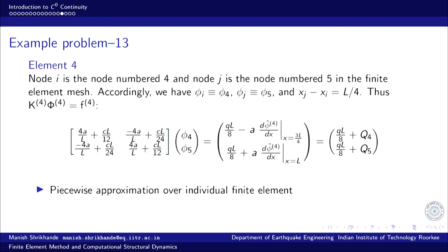For element number 1, we developed a linear interpolation between phi 1 and phi 2, and developed the linear approximation for phi over element 1, and then evaluated the weighted residual statement, weak form, integrals evaluated over this subdomain, and whatever algebraic equation presented itself, we assembled that as the element level equation, and so on for all the 4 elements.